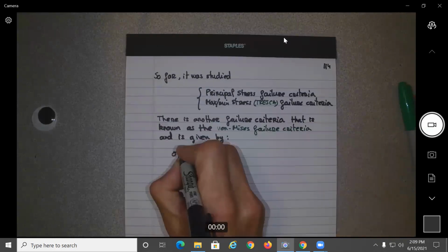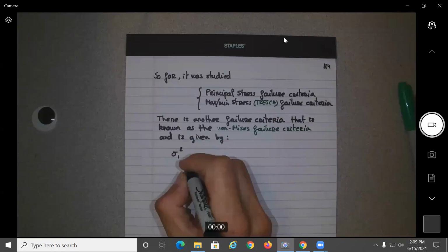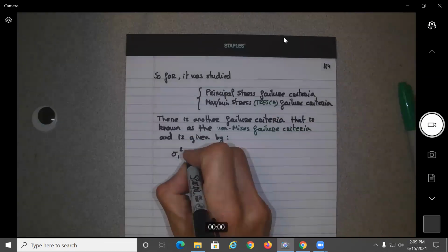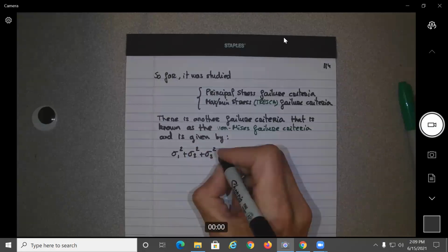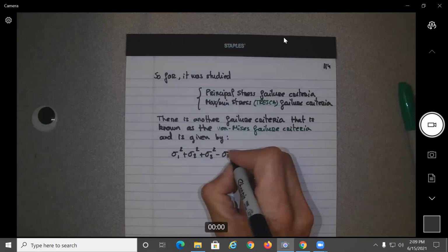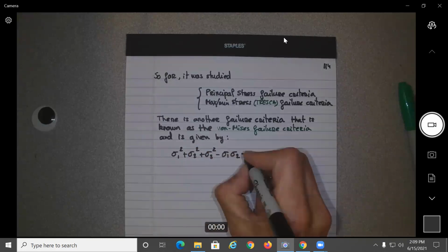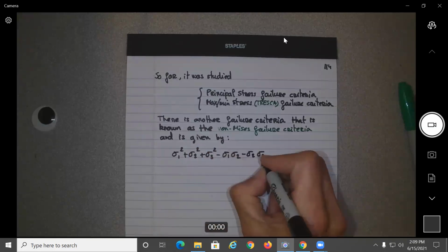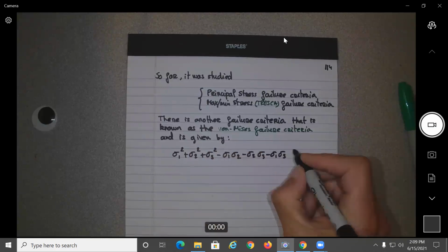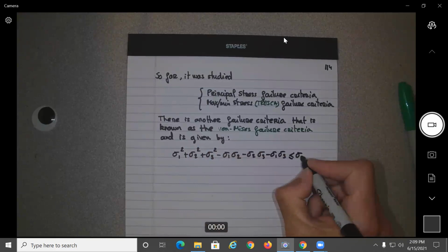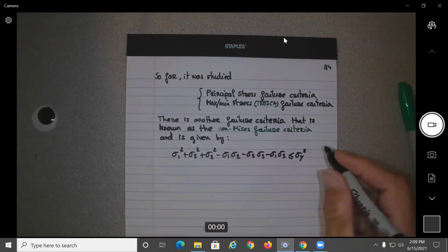So once you calculate all the stresses, you find the principal stresses. This is in 3 dimensions, so the third should be 0 for all your cases. And this is the yield value squared.